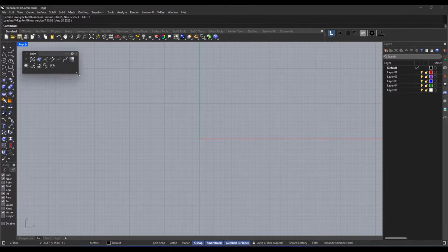Let's talk about point cascades. This is all about the different ways you can draw a point. First up, we've got single point. The point command just draws a single point object at a specific location. You just pick a location for that point object. Next, multi-point. The points command draws multiple point objects. You just pick the locations for these point objects and then press enter.